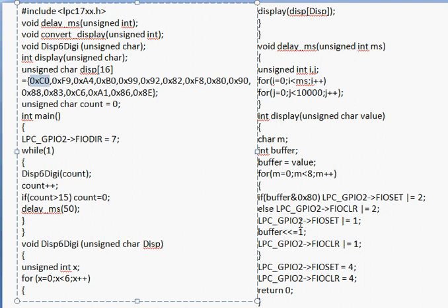Previously this bit is reset, because GPIO you haven't used it. So that is set to 1, which is P20. P20 is meant for providing the serial clock. Now the serial clock, initially it was 0, now you make it 1. Now the data goes to the shift register module.